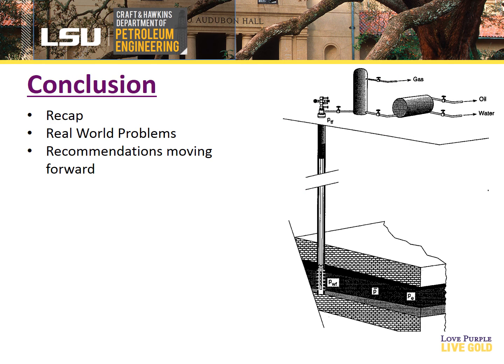In conclusion, for the base case, the system is already producing near the separator volume limits at about 5,000 barrels per day. Given the dip in the dual flow line profile, slug flow regime is very likely and needs to be accounted for as a safety factor. Also from our simulations, we concluded that the tubing and flow line do not seem to be limiting factors.